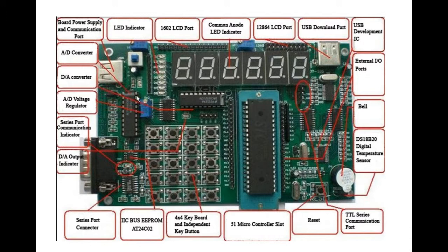Eventually that 8 bit digital signal is the output of this chip, transmitted into the microcontroller, and the microcontroller does the relevant logic calculations based on the information received from the AD converter. So that's the AD and the DA converter.